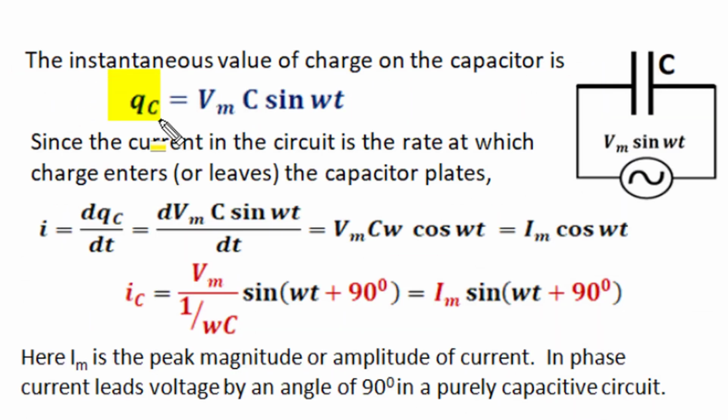So instantaneous value of charge on capacitor is directly proportional to voltage applied across it, and as voltage increases, charge on capacitor also increases and becomes maximum at that instant when supply voltage is at its peak value, and as voltage decreases, charge also decreases, and after every half cycle this charge alters its polarity or position.